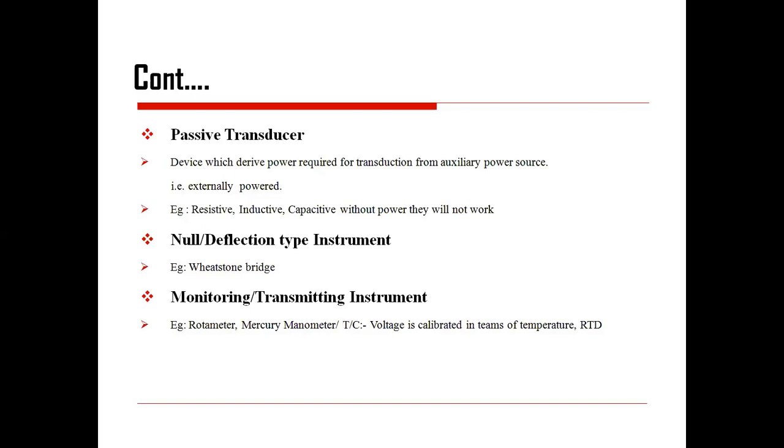Now, the monitoring one, rotameter. Suppose we take an example of a petrol filling plant or petrol pump. At that time, when we are trying to fill petrol, we specify a quantity that is indicated on the display. Similar is the case with the rotameter. What is the flow? Depending upon the variation in the flow, your rotameter float will vary, and at the upper scale we read or record the reading. That is nothing but the monitor.